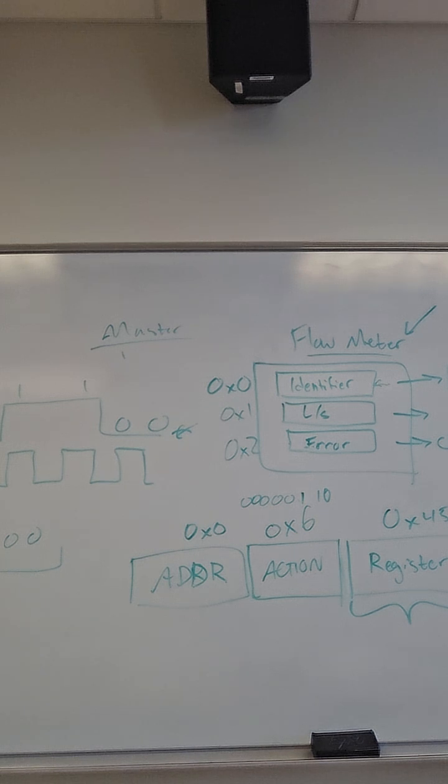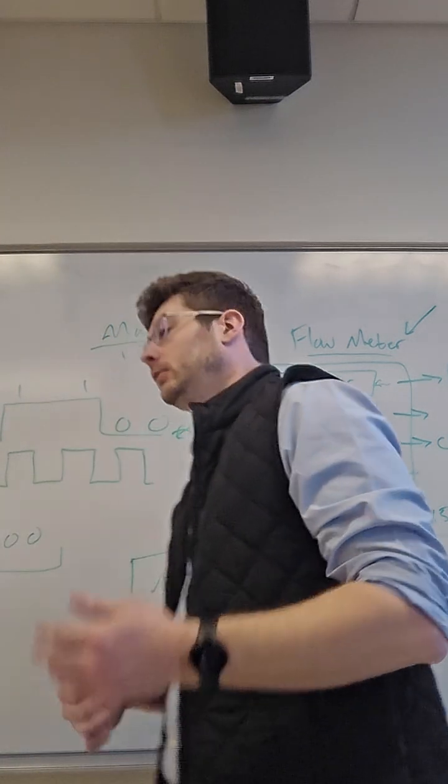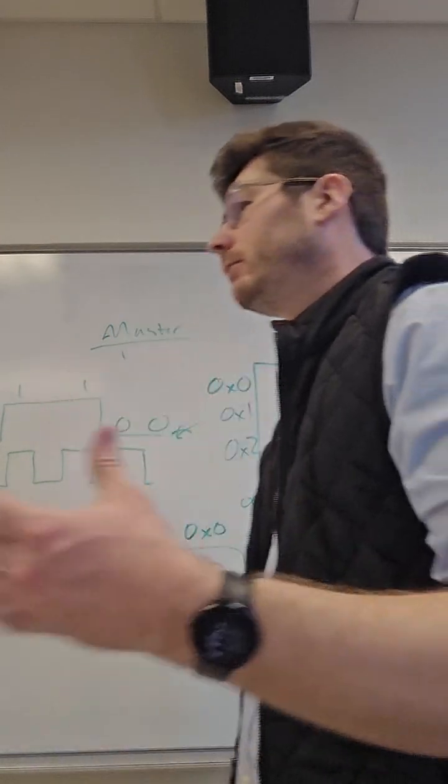But in another part of the system, it might make more sense to have a PLC talk to another PLC that's talking to equipment, right? And each of those has its own devices that it's responsible for, or even just one device per one PLC, depending on what that device is doing and where it's located, and how processor intensive whatever it's doing is.